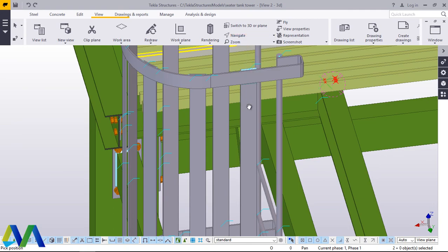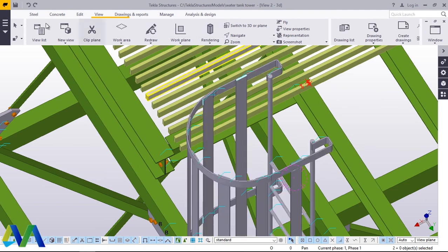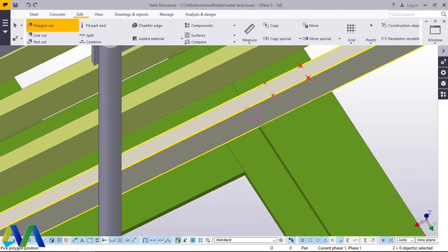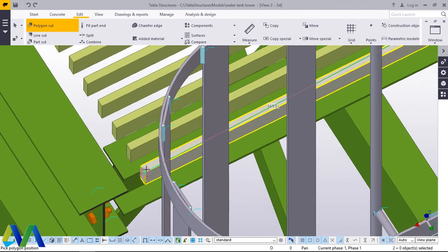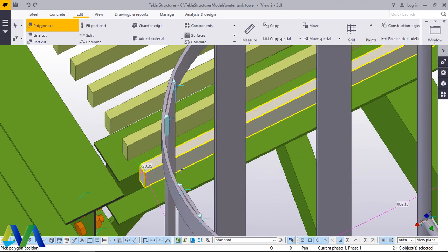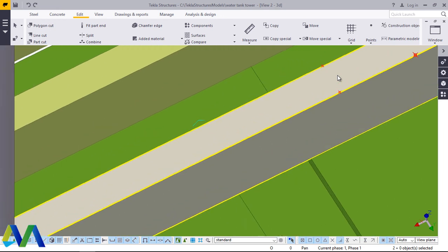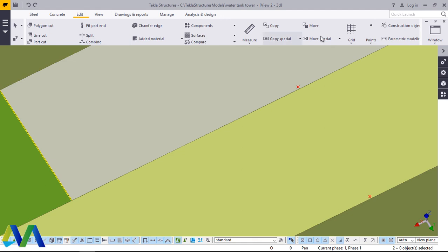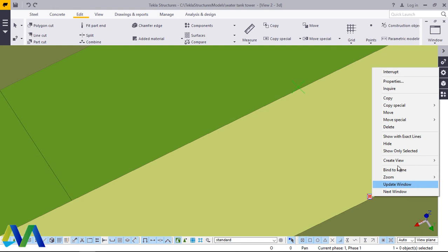Now we'll come to navigate, turn this round like this. Then come to edit, polygon, pick on this, snap right there, and run all the way to this end, and snap right there, and come back here. They're not in the right positions. I'll come back to edit. We'll do away with this spot in that point.